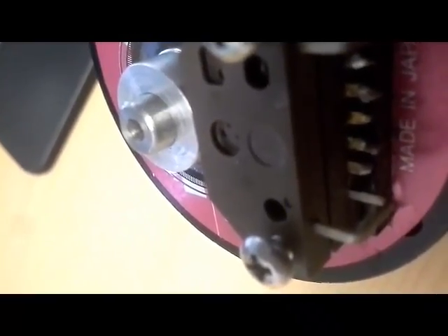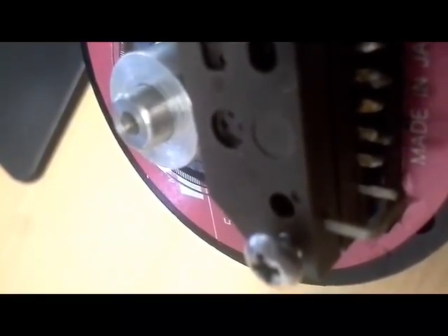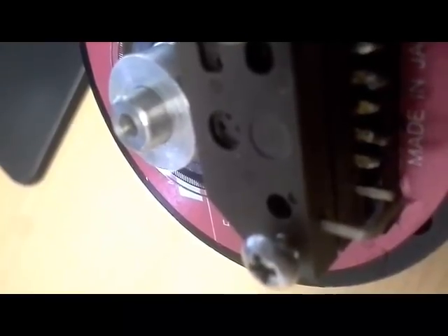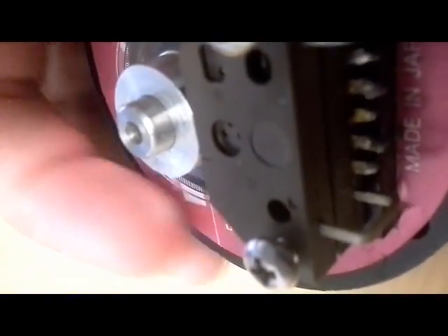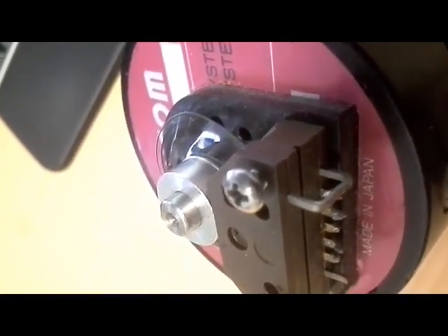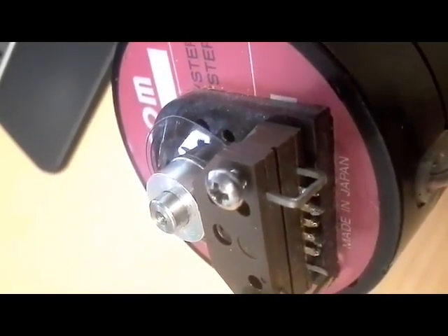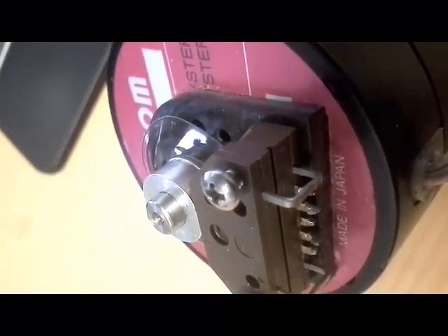When you buy a motor with an encoder on it, the encoder includes a specification that tells its number of lines. You might find an encoder with something like 512 lines. That number tells us how many of these clear lines are included around the entire circumference of the clear disc. And that tells us the resolution of the sensor. In other words, if the encoder has 512 clear lines, we can detect an angle change of 360 degrees divided by